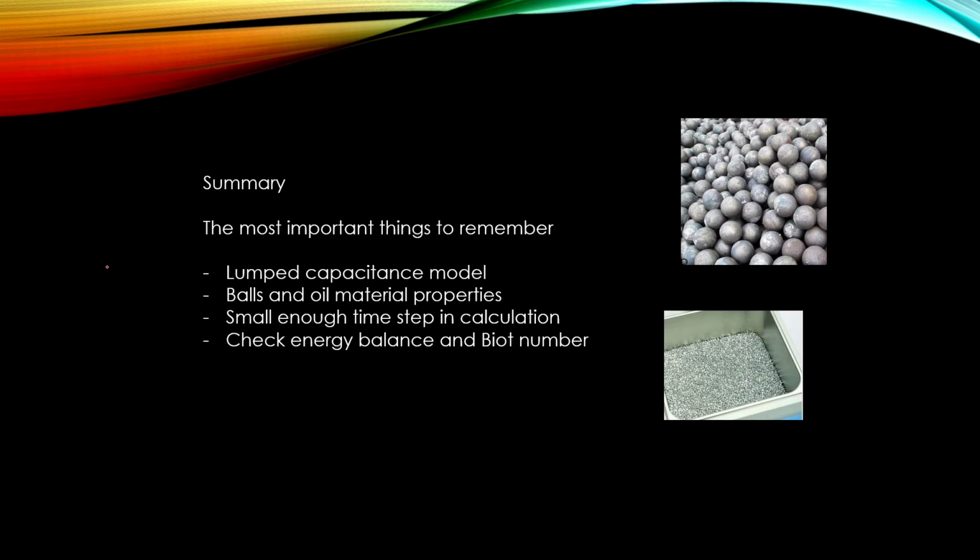As a summary, I would like to say that when you need to calculate this kind of cases, this lumped capacitance model is often good enough. And you need to know those balls and oils material properties. And when calculating, use always a small enough time step in your calculation. Check this energy balance and check this Biot number.